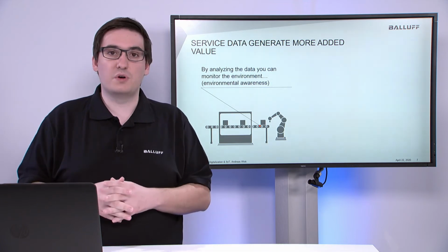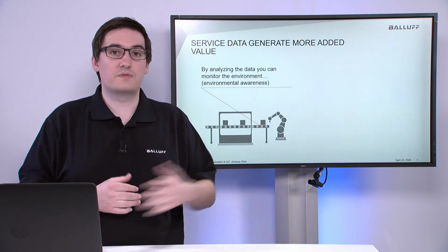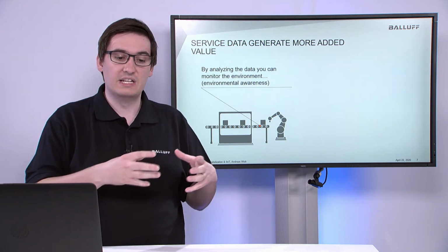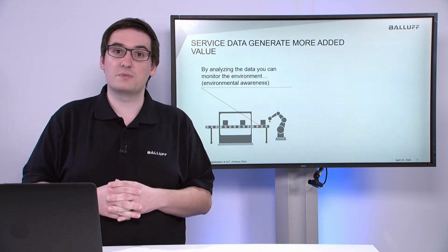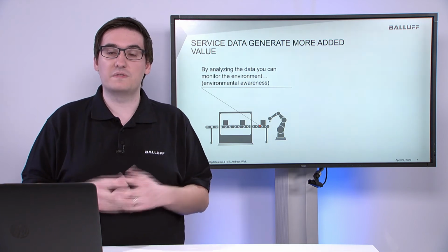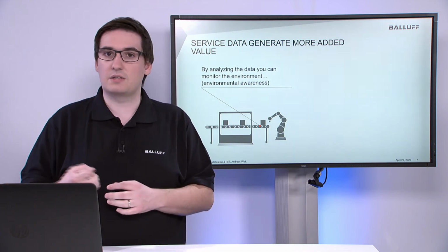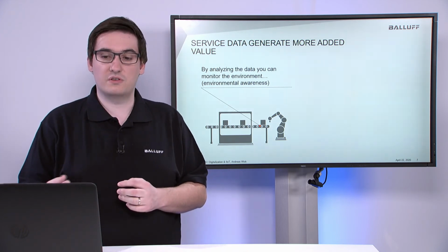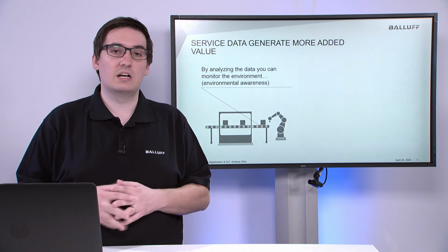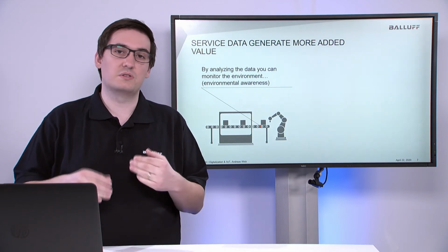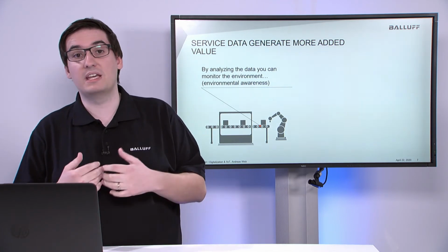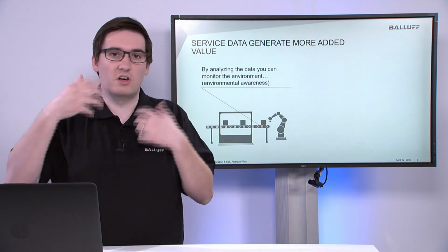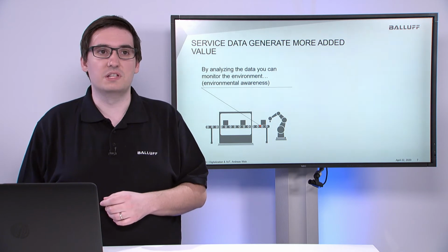And the same goes, for example, for the use of current data. So if you have a power supply which is providing you with its current consumption, you can detect whether, for example, over days or months, your motor is using more current and more power. And this could lead to the knowledge that you may need to maintain your couplings or stuff like this. So these are all thought experiments you can do here.